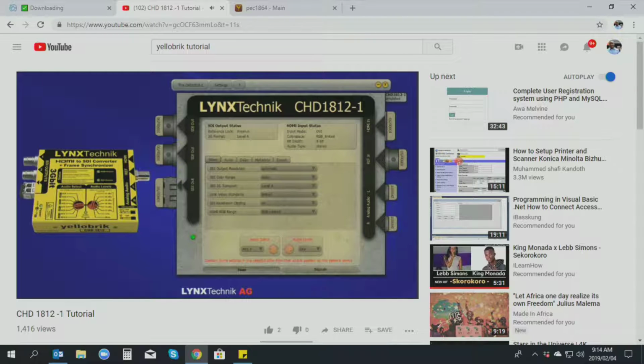Again, we don't have any way of scaling that down, so what we do is you can take it out of this automatic mode where we negotiate the highest resolution over EDID, and you can jam it. So if I'm a 720p plant, I can go 720p. Now, let's not set up a scaler. What that's done is that's basically now when the sending device inquires of the module over EDID, gee, what's the highest resolution you support, we answer back only 720p.